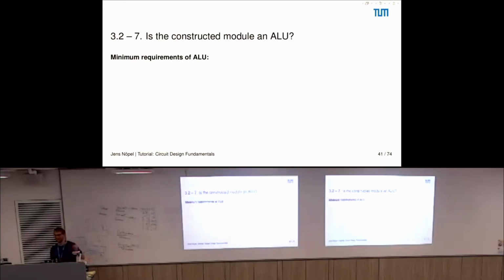So I've heard addition, that is true. Inversion, yes. And? So we definitely need addition. We need inversion, and we need either an AND or an OR. And this is the minimal set. And with those three things, you should be able to do all operations you need.